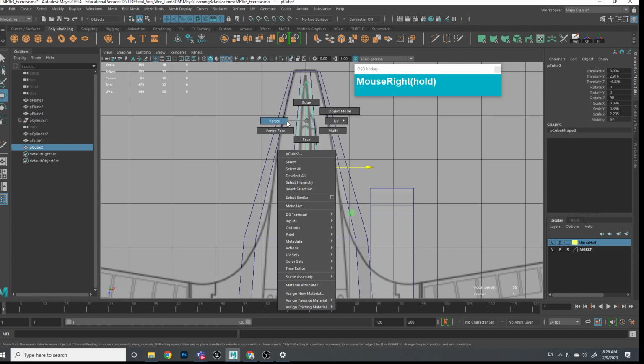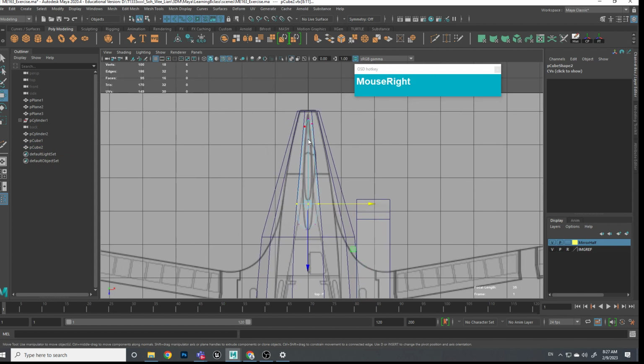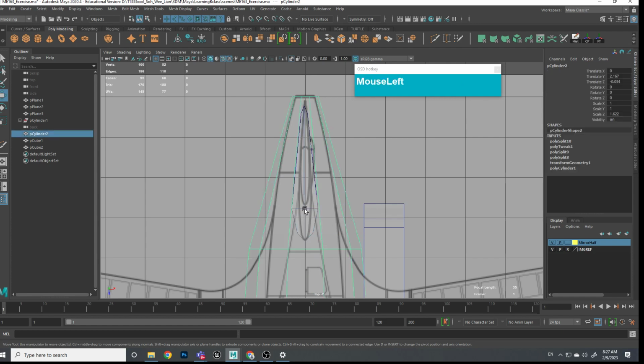The only thing that is not so correct is that it's not very symmetrical. We can fix that quickly by using the scaling tool. So grab this row of vertices over here, the center vertices. Use scale, and then to center it. Then these 2, use scale to line them up together. Right now I'm just eyeballing. I'm not using any mirror here. So just manually moving the vertices until it matches my reference. Select these 2 vertices, just drag.